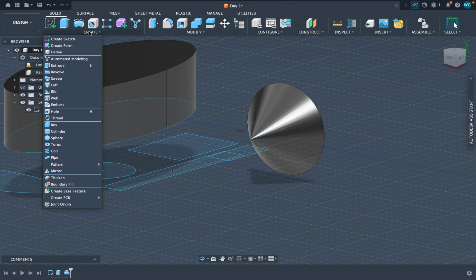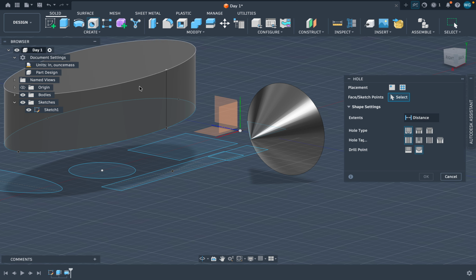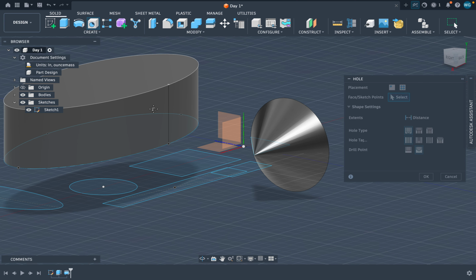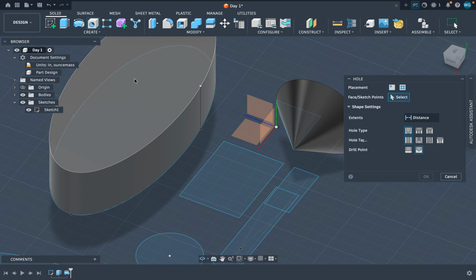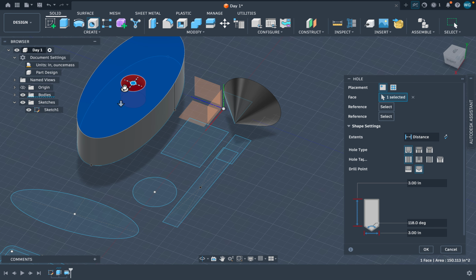Okay, next is hole. A hole is used to make an opening inside a 3D model. For example, if we use this oval again, we press the face where we want to make the hole. In this case, it is right here, and we are shown the hole. Then you can make it bigger or smaller, and you can just type right here. Making the diameter this way is the same as moving this arrow.